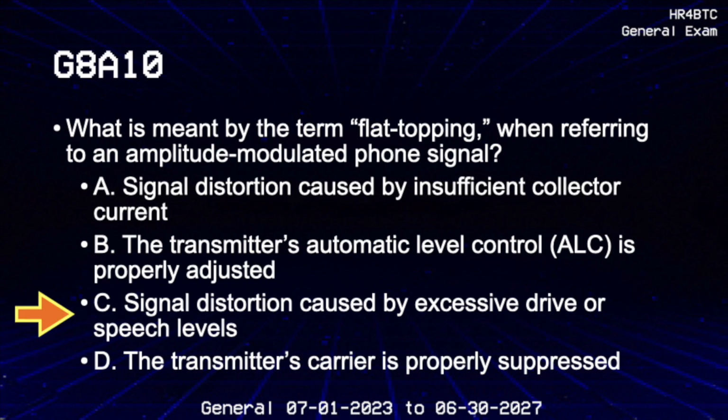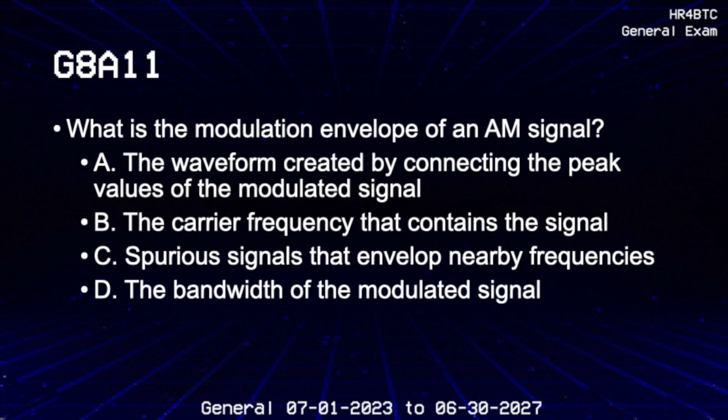What is meant by the term flat topping when referring to an amplitude-modulated phone signal? Signal distortion caused by excessive drive or speech levels. What is the modulation envelope of an AM signal? The waveform created by connecting the peak values of the modulated signal.